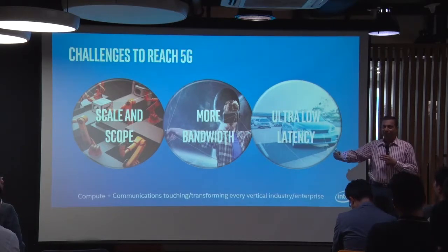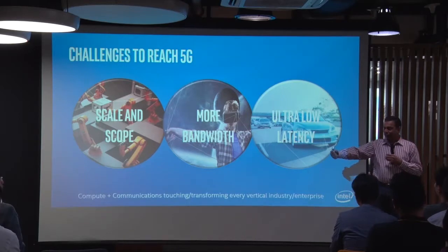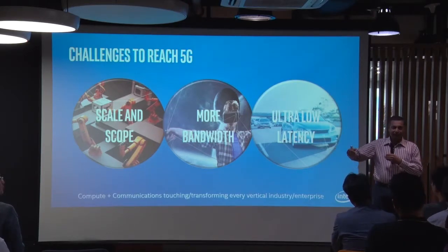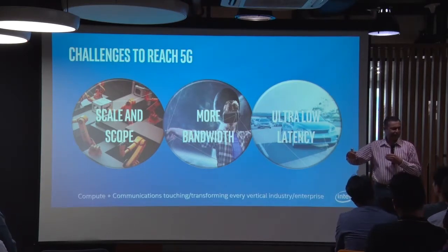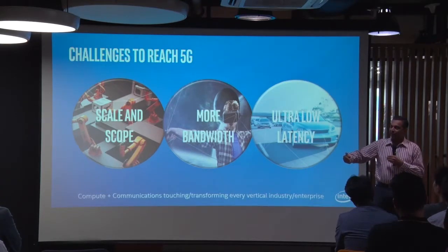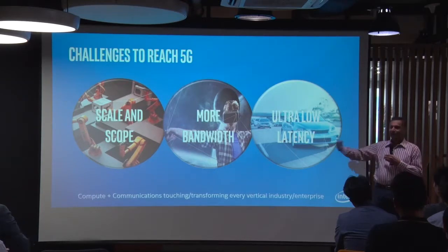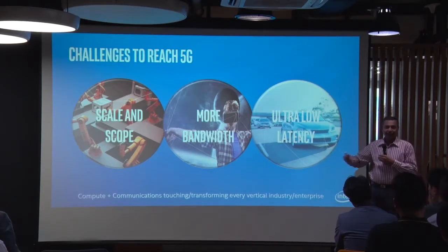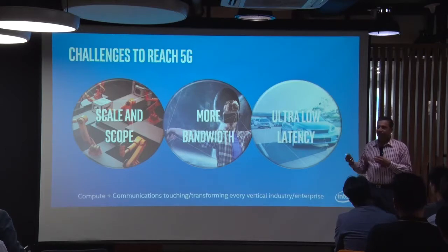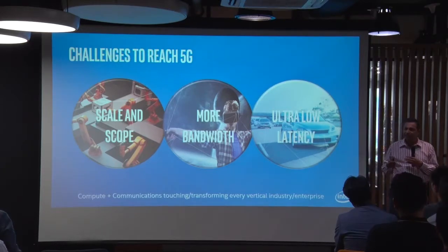It's a moving car, and the distance between the cars is relatively small, something like 20 feet. If you compute the speed at which the car is moving and the distance between the cars is only about 15, 20 feet, and back-calculate from there, we can guess how much reaction time the following car has to react to the actions of the first car. It's in the order of microseconds, hundreds of microseconds, tens of microseconds.